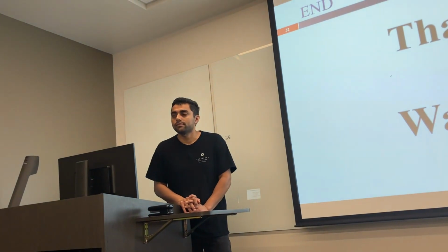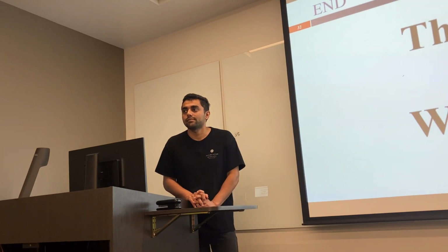Do you think that overshoot is something you can tune out of the PID controller, or have you messed around with tuning that at all? Yeah, I did. I found a paper with some rules of thumb about how to tune PID for mobile robots. It would say, for example, first let it wiggle, then divide the P by half, something like that. I tested that. Also, I put random numbers, but maybe we can have an experimental design, like 20 experiments, to see if it can be further fine-tuned.